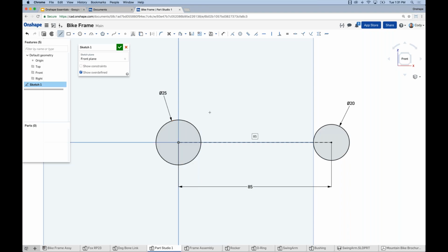So we'll sketch our first line. Notice as I move my cursor over the circle, it highlights, indicating, hey, you're creating a constraint to this point on the circle. Left click, and now I have a line that's attached to both circles. And I'm just using those visual cues, the highlighting, telling me you're creating a constraint. So I've got my simple line joining the 2 circles, and I want to mirror this line about this construction line, which is why we needed it.